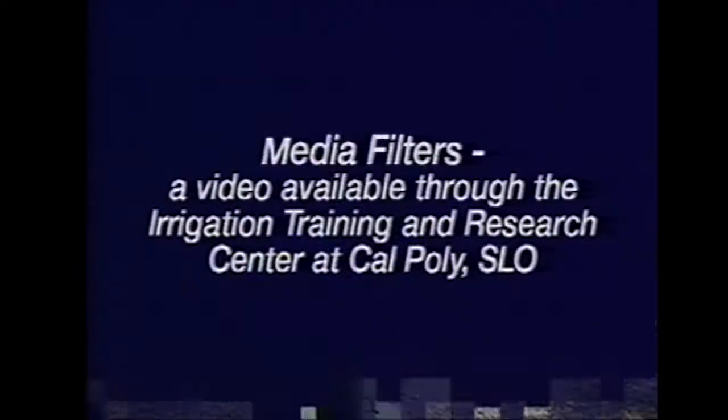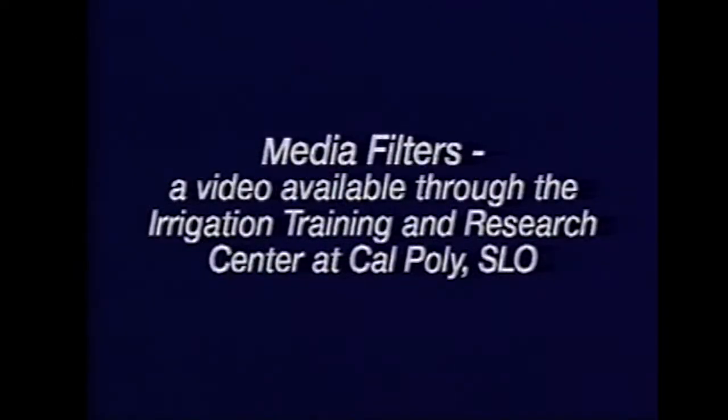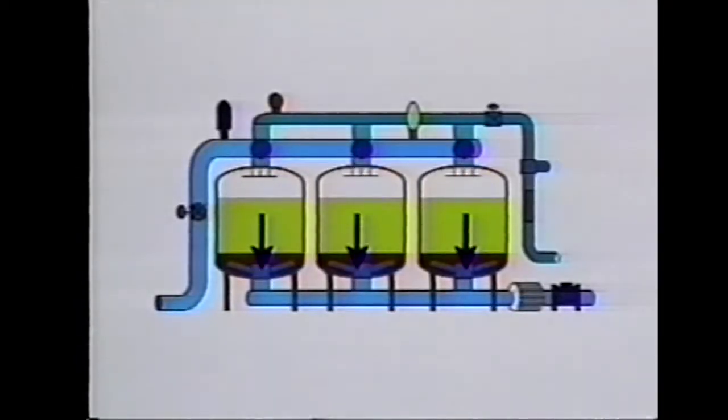There are so many important selection, installation, and adjustment details for media tanks that the Irrigation Training and Research Center has developed a separate video just for media tanks. Therefore, this video will only touch on a few items. Media tanks provide three-dimensional screening of materials, as the dirty water flows through a layer of special crushed granite. During filtration, an equal amount of dirty water flows through each tank. Dirt remains behind in the top of the media bed.